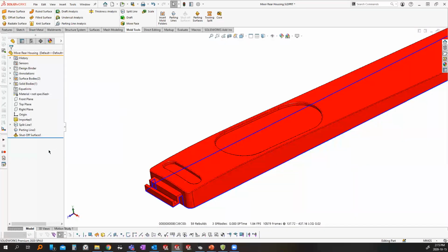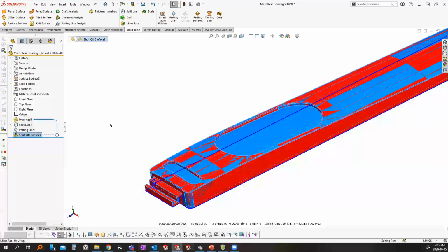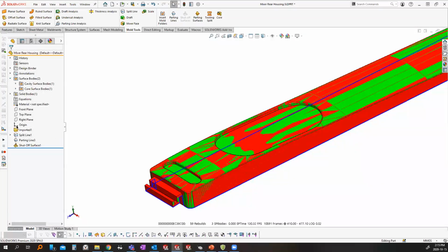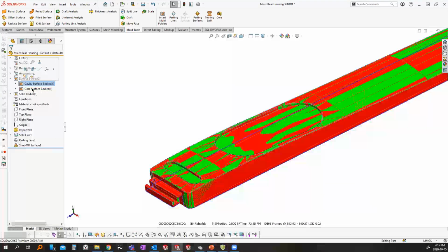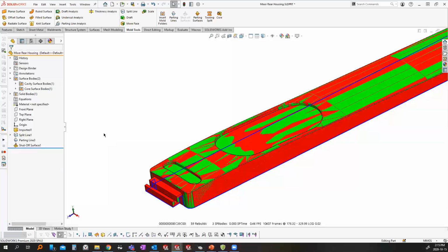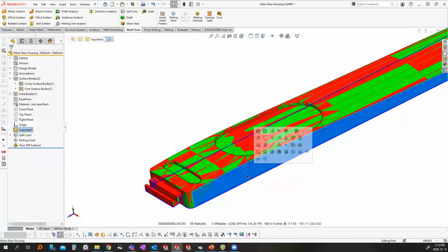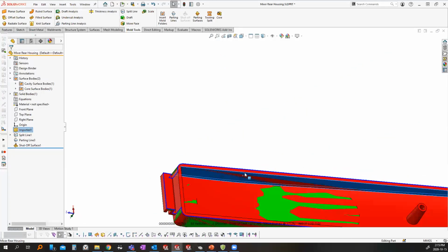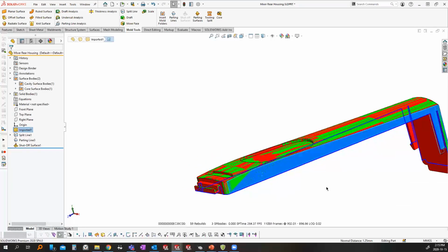So you can see a couple things have happened after just these first two commands here. If I go into my surface body folder, you'll see a cavity folder and a subfolder for your core surfaces as well. What it did in the background is it took my inside and outside faces of this part and copied those surfaces over, essentially putting them into the corresponding folders.